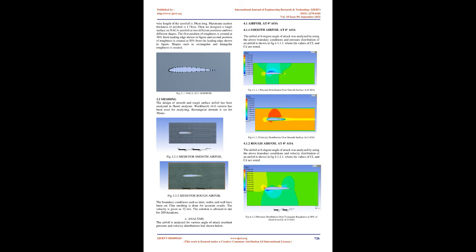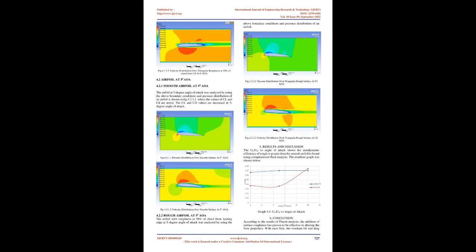An experimental investigation on the effect of surface roughness on NACA 2412 airfoils is performed. The experiments include measurements for the pressure distribution, drag coefficient and lift coefficient. Two different rough surfaces are analyzed and their data are compared to those over a smooth surface. Measurements are obtained for angle of attack in the range of 0 to 10 degrees. Also, measurements of the velocity and turbulence intensity profiles are collected for the flow around the airfoil at various pre-chosen stations. Design and meshing. 3.1 Design.